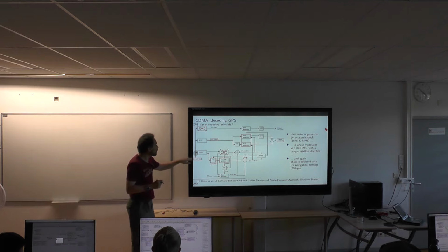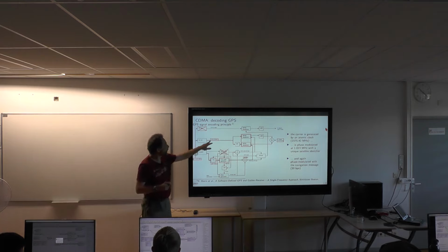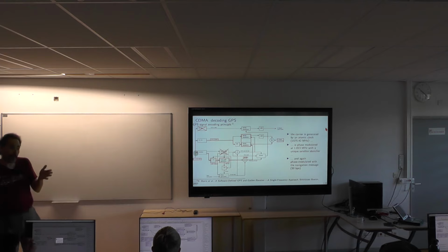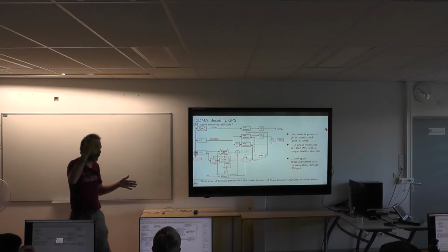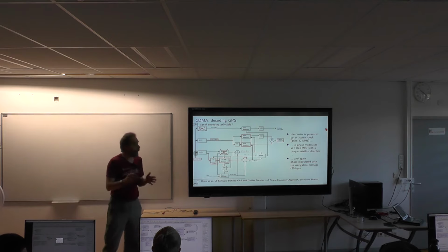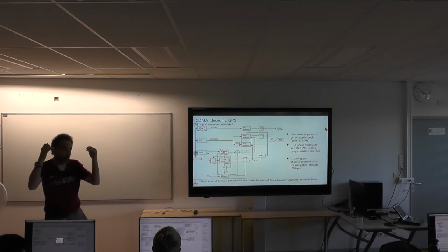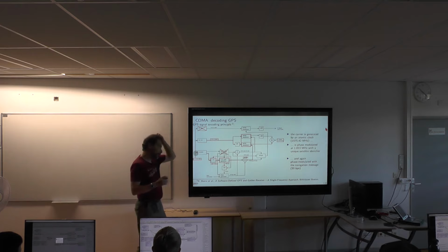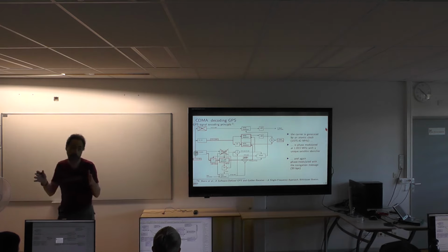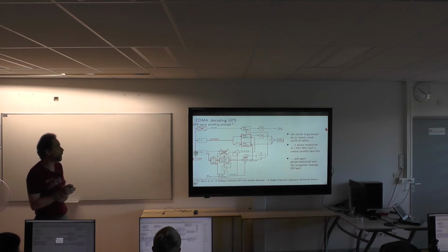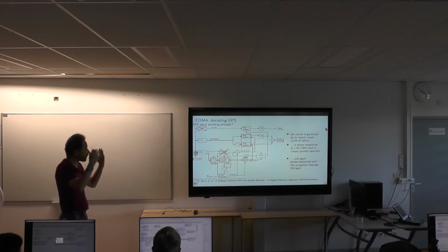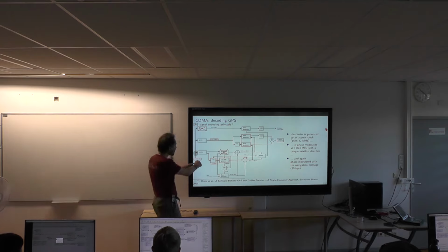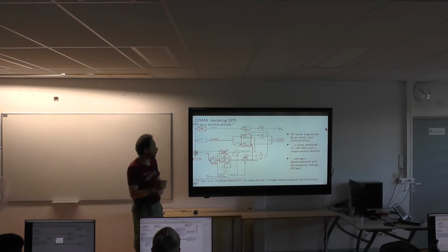And this frequency is multiplied by 154 to get the 1.57 gigahertz carrier in the L band. The L band is selected to have little impact of tropospheric delay. Troposphere is cloud, rain, moisture in the atmosphere. It also has little ionospheric impact. The ionosphere is the upper layers of ionized plasma. So the L band is dedicated to space communication and is much less impacted by troposphere, unlike, for example, Ku or Ka band at much higher frequency, where the impact would be stronger. So all the satellites are broadcasting at 10.23 multiplied by 154.